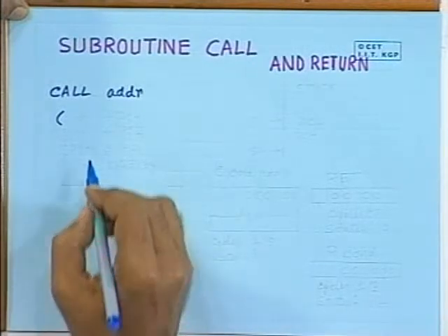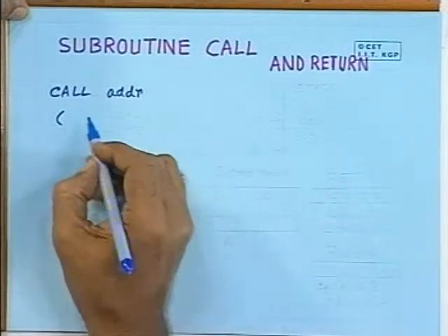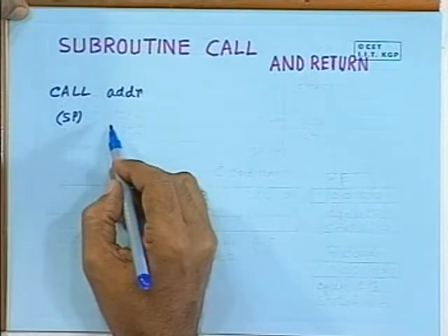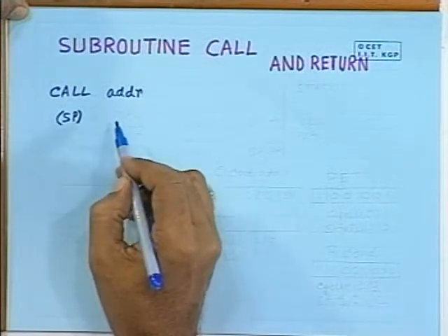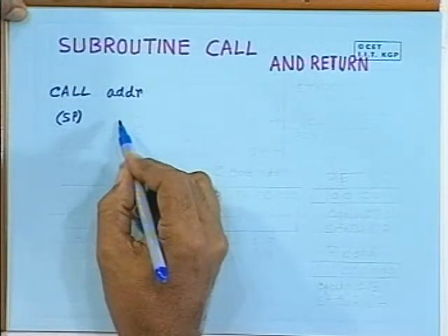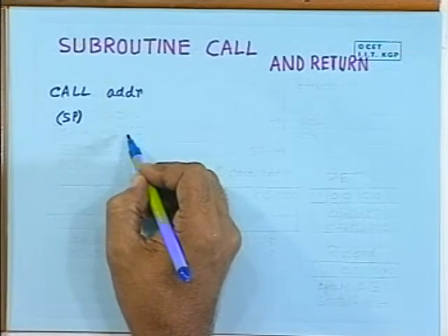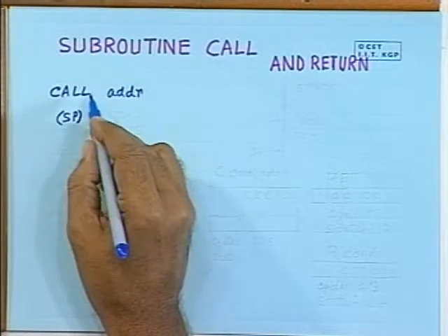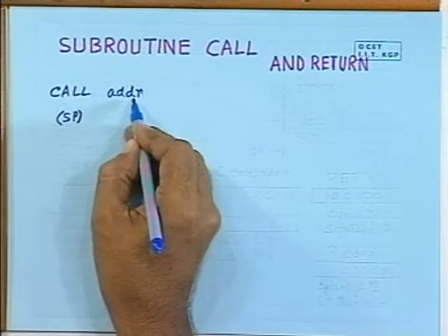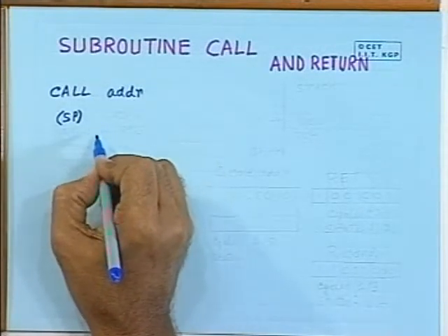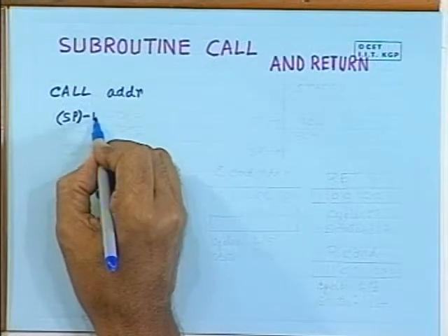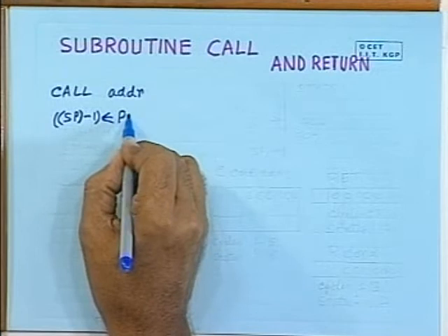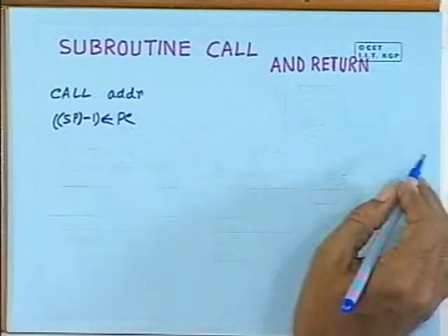You have to load the program counter with the new value, but before that, the program counter has to be saved so that you can return to this point. For example, the operation performed by this subroutine call instruction is like this: the stack pointer minus 1 is the address which is loaded by the program counter high.